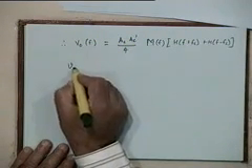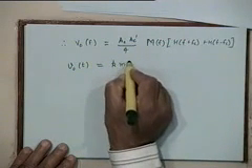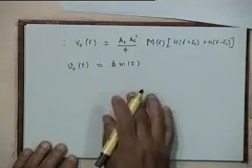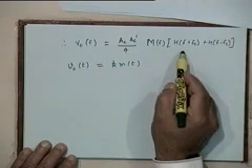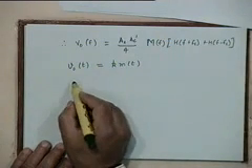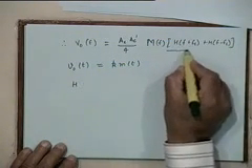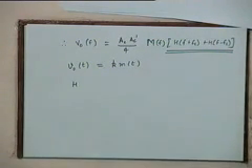What do we want? We want our V naught of t to be proportional to m of t, k times m of t, right? So what does that tell you? What can we say about the filter H(f)? What condition should it satisfy so that this happens? This function of frequency which is coming from these two terms, which are coming from the filter transfer function, should be equal to a constant value, right? They should not be a function of frequency, right? That's what it means.